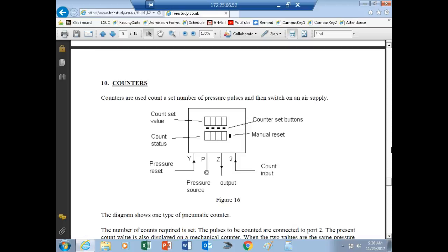So ours is what we call a down counter. You all know what that would probably mean. We'll set a value in it, and then every time it gets a pulse on the input, it should count down. And when it gets down to 0, it's going to generate an output, right?